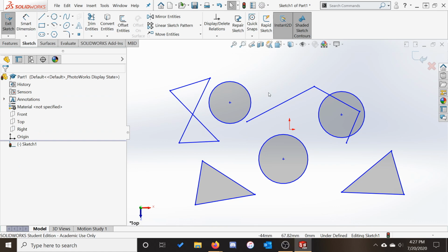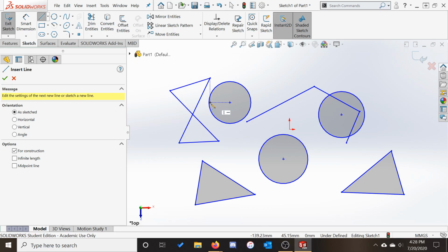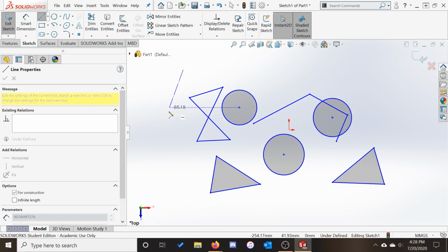Next up, we're going to hit construction geometry. Oftentimes, it can be useful to define things using other shapes, to show that several things are along the same line, or to use an arc or a circle to define some more complex geometry. The most common form is a center line or a construction line, which can be found in the drop-down next to the line tool. It functions identically to the line tool, and it will have more uses in the future.